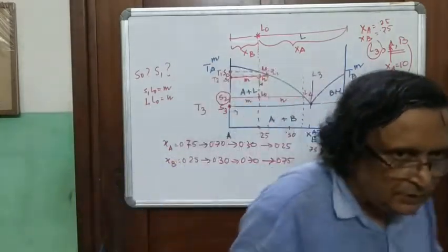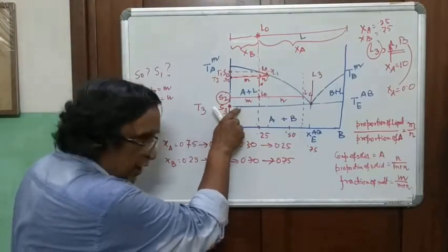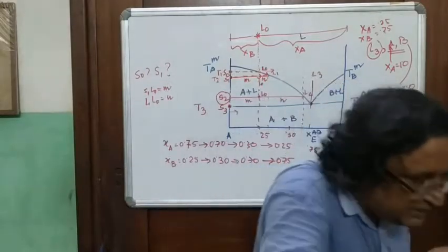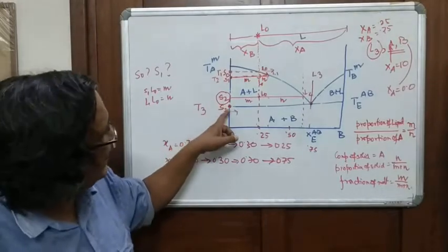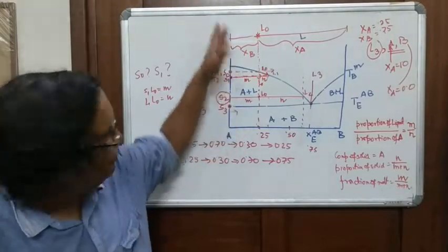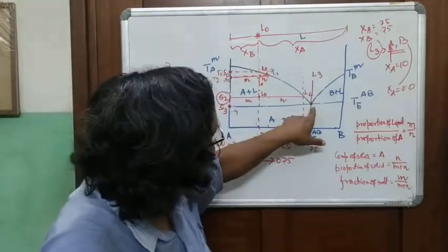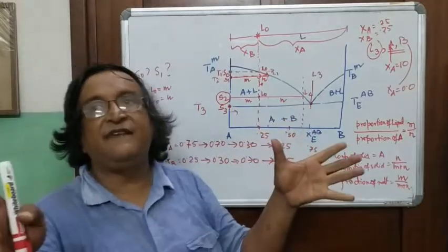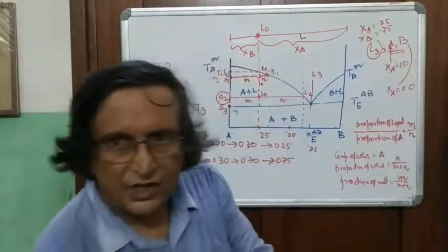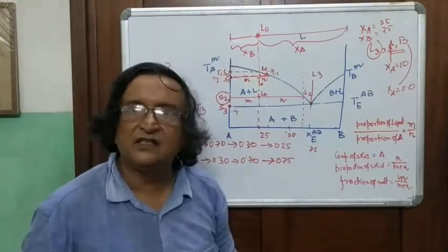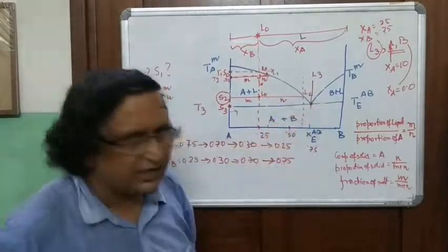So this composition S3 will have to move inwards to accommodate more A and new B. This point cannot stay on the vertical axis anymore, but has to move along the eutectic. Why eutectic? Because this is the only point in the phase diagram where a melt coexists with two pure solids. There is no further melt in this diagram. Melts don't exist below the eutectic temperature.